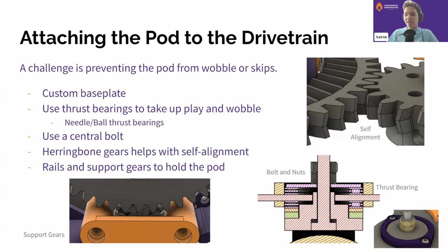It's been an issue for some time, and the closest solution we could find was one that I will post later when we post the presentation. It involved reading the current velocity and setting a target velocity for the robot. But because this field was so specific and it has such small channels the robot has to pass through, using a field-centric drive that caused that drift side to side made it very, very difficult to control.